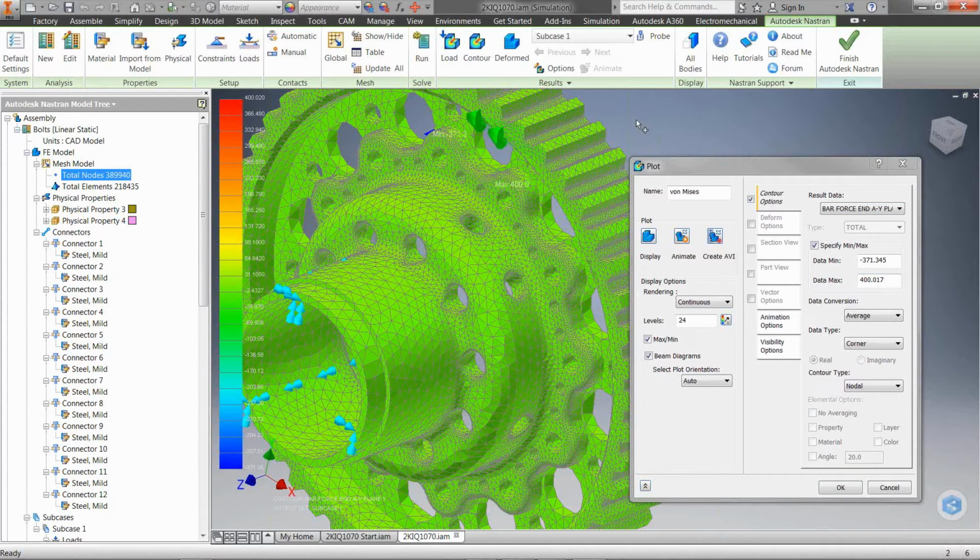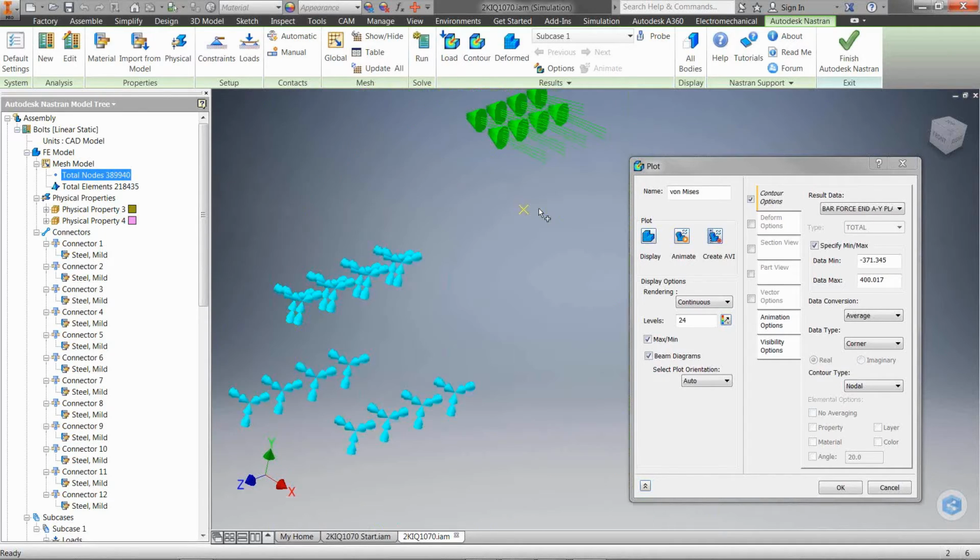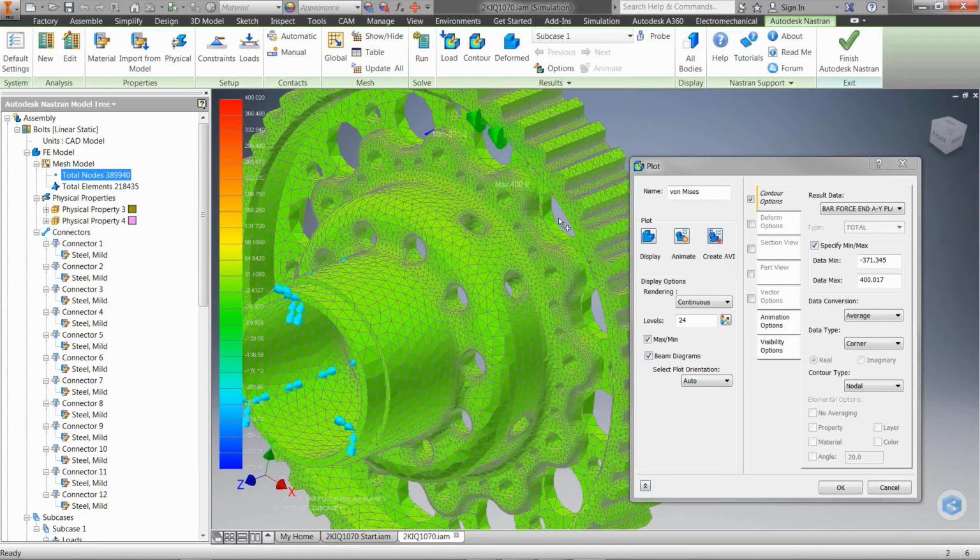So again, this gives you a lot more information than what we saw earlier. It was great in the bolted connection that we were able to do a quick calculation based off of formulas that we would typically find in the engineer's handbook. But there's nothing like actually seeing this visually and being able to work with it and make changes, go back, maybe change the bolt diameter size, or maybe change this hub. Maybe we want more holes.